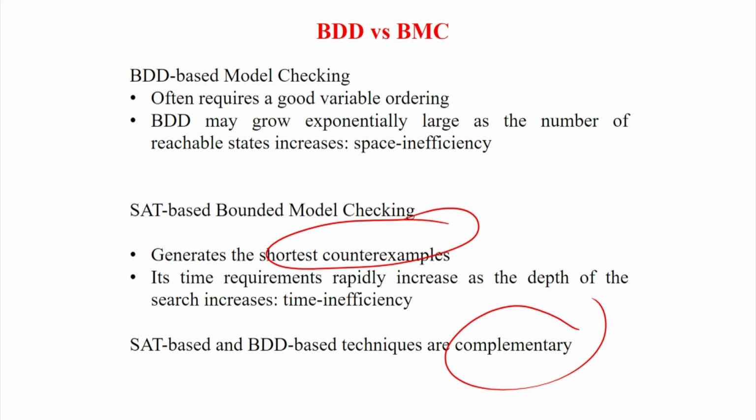As you might be feeling, this is also the last lecture of this course. In this course we have tried to discuss the traditional CAD algorithms, and then we have seen the different optimization problems and how we have changed or modified these traditional algorithms so that the complexity can be handled. But still, for many of the cases, we have not reached the desired level. Like if you take verification, we have not even reached the level where you can verify the whole SoC and NoC in one go. Basically because either you have to go by symbolic model checking, or if you are going for abstract diagrams, we do not have very good algorithms for model checking on those high-level abstracted diagrams. So there are a lot of gaps.